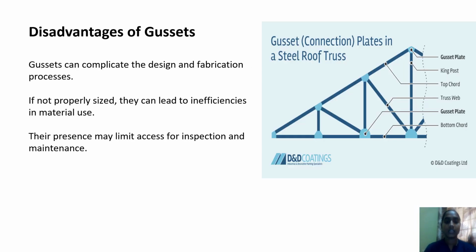Disadvantages of gussets. Gussets can complicate the design and fabrication process. If they are not properly sized, they can lead to inefficiencies in material usage. Their presence may limit access for inspection and maintenance.